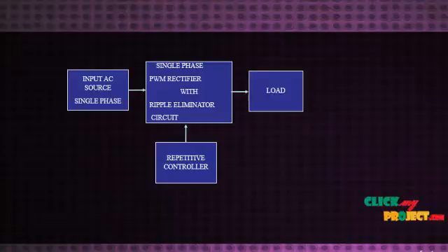A single phase supply connected to an alternating current electric motor does not produce a revolving magnetic field, and single phase motors need additional circuits for starting, and such motors are uncommon above about 10 kW in rating. Single phase AC power systems peak in voltage at 90° and 270°. A cycle completes at 360°.